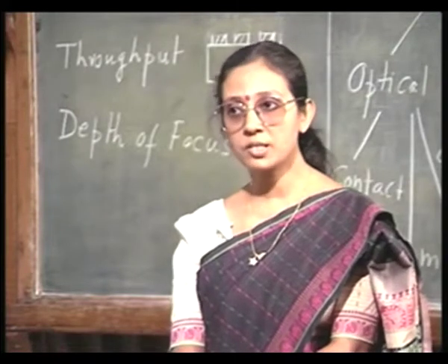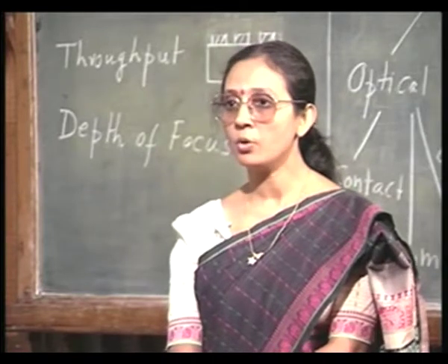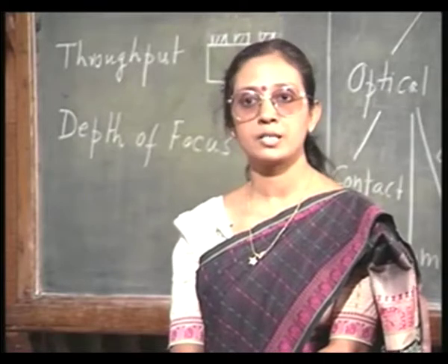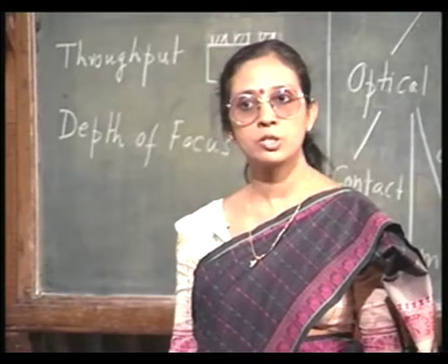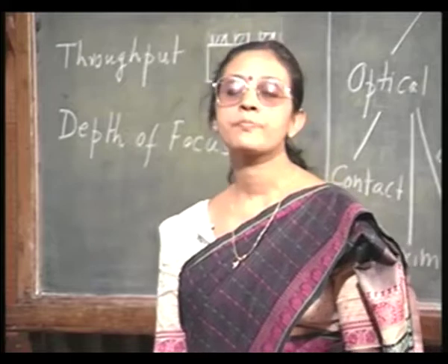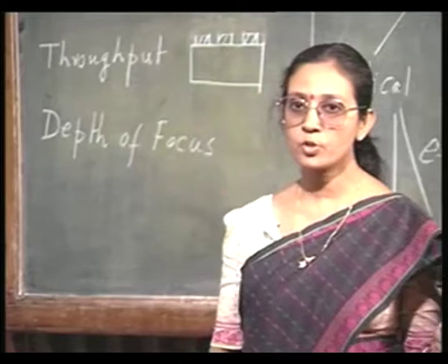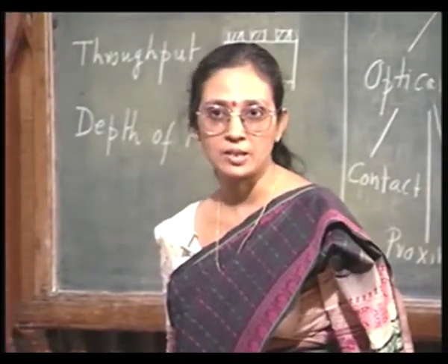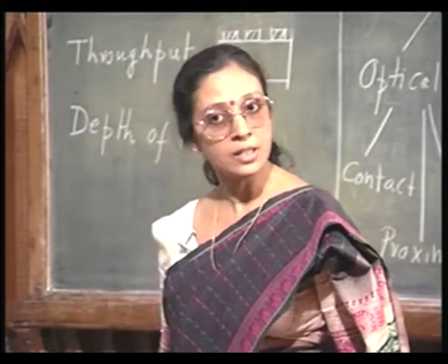So that those regions which are exposed to the radiation will become soluble when you put it in the developer solution. Whereas, the portions which are unexposed, they retain their original property and they are not dissolved in the developer solution. So, this is in essence what a positive photoresist is. The exposed regions become softened because the photosensitive material is becoming soluble, that is allowing it to get dissolved.